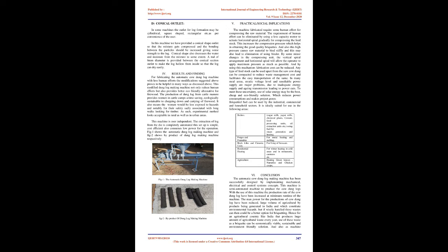C. Vertical spiral. In general machines there is only one horizontal spiral in the grinding unit. The modification in this machine is that a vertical spiral is provided just below the hopper inside the vertical cylindrical portion. The spiral is attached to the mixing blade rod.